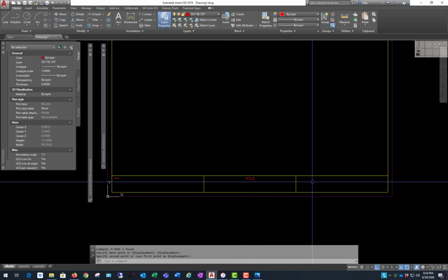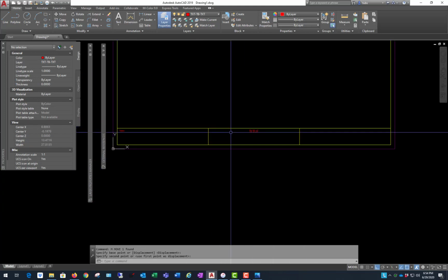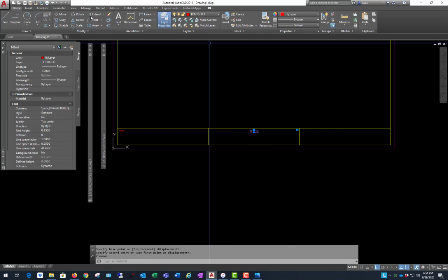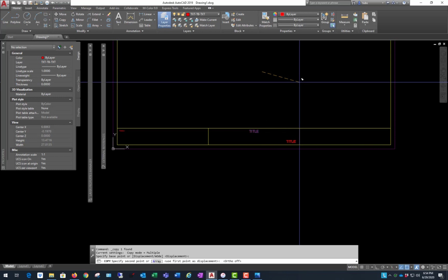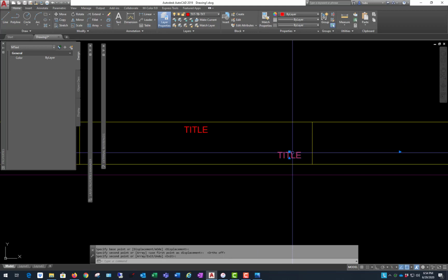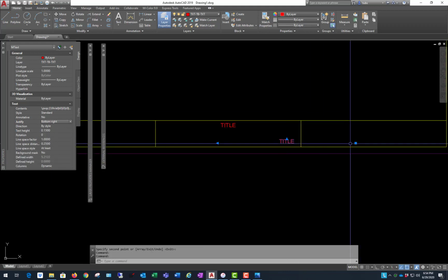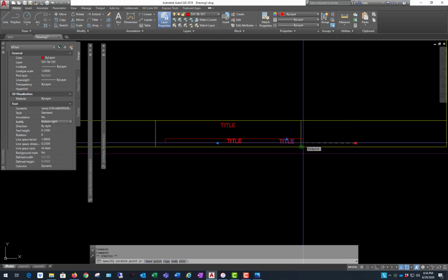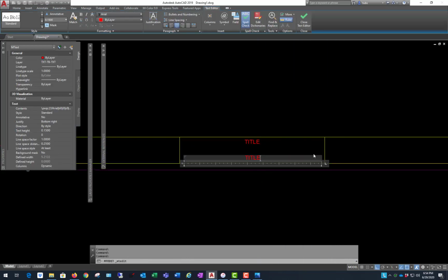So just enough to get the job done. What else do I have on here? Oh, a date. I'm going to copy this again. And I'm going to take off ortho because I want this in my lower right-hand corner of this sub block here. I also want it to be bottom right justified. This means that when I go in there and change it, it'll hold that point. I'm going to double click in there, select it, make sure this is right justified.